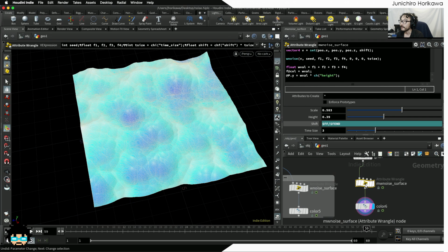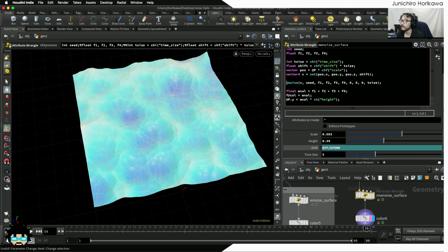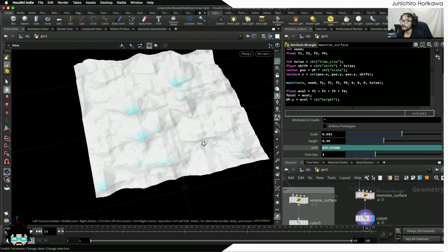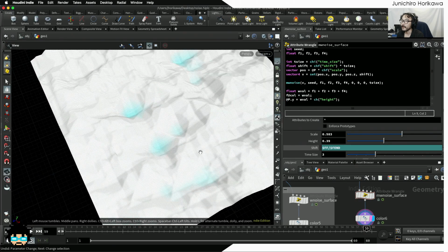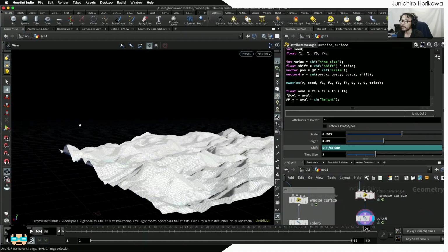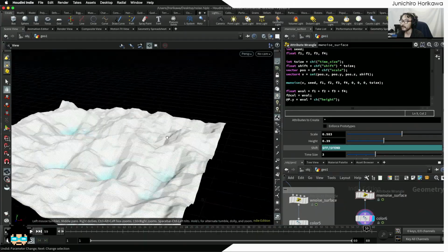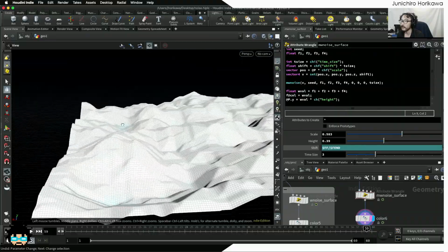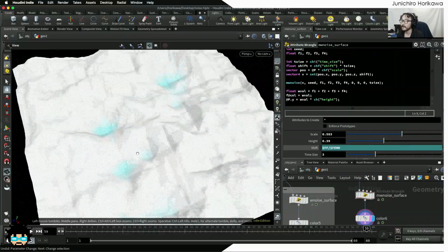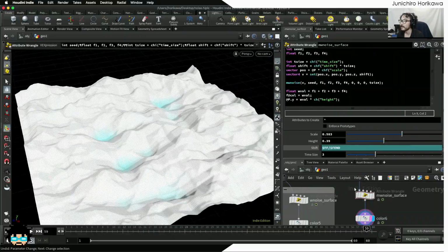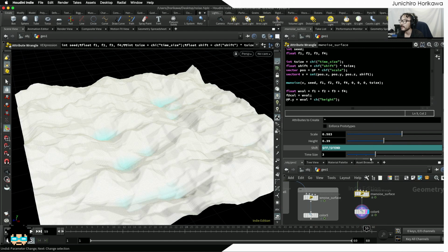Okay, so what you need to do is just rename this W noise to MW noise, and that's it. In order to use the Manhattan noise, you just add M. As a result, you get something like this, more like a landscape or mountain landscape, a bit artificial, low poly, but it looks like a mountain landscape. So let's try to color this in different colors.